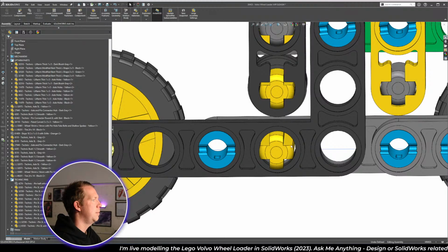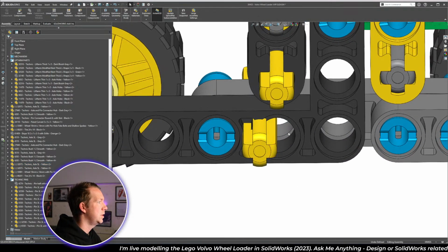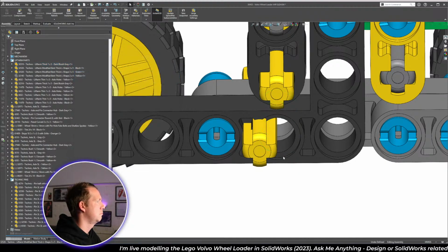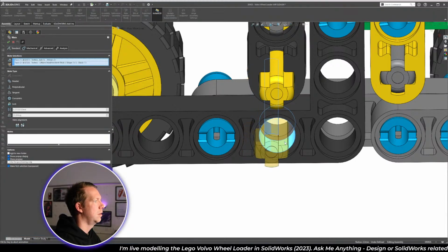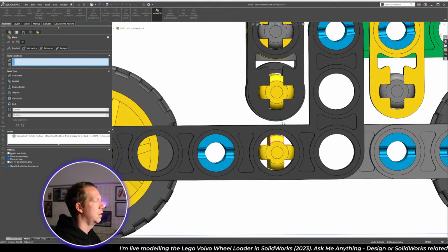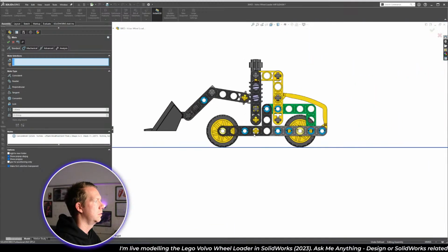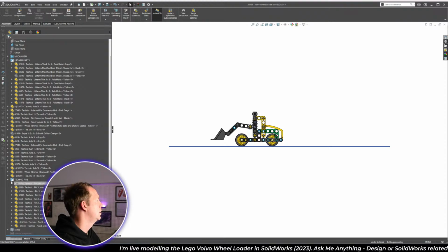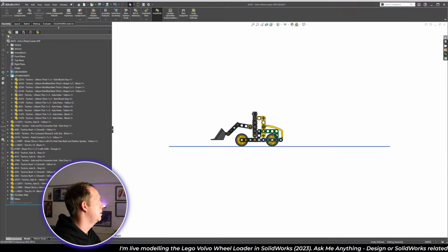Just going to delete that mate. Just check those holes. They're okay. All right, it's concentric now. Let's show our parts again.